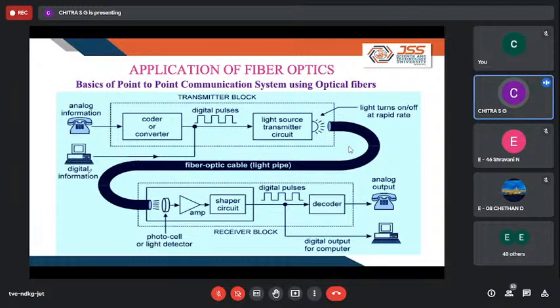And another one is we cannot bend the cable too hard. The cable has to be taken care of when you're dealing with it at the corners or when you're spooling the cable. There should be no such macroscopic or microscopic bending. That means you should not put too much pressure on the fiber, where radiation loss arises. Also, because of temperature variation there might be contraction and expansion of the optical fiber, and a loss of signal might arise.